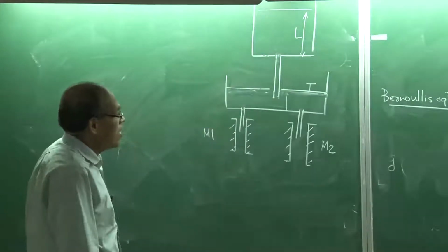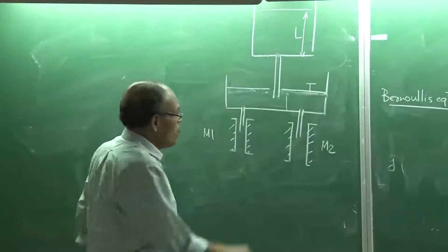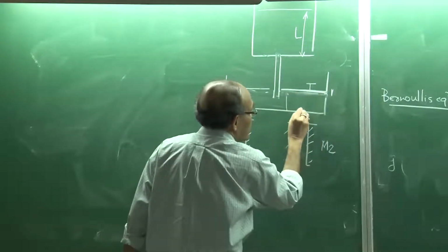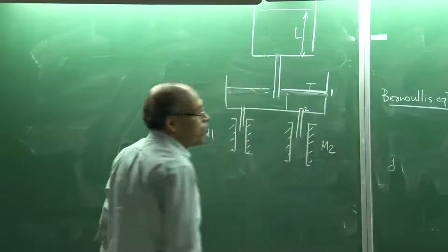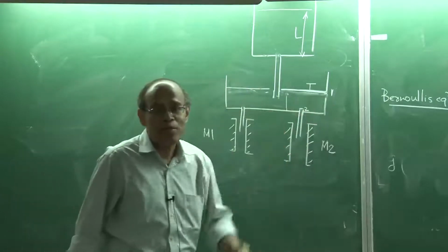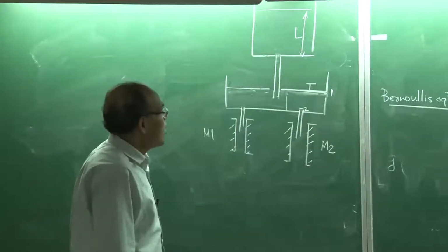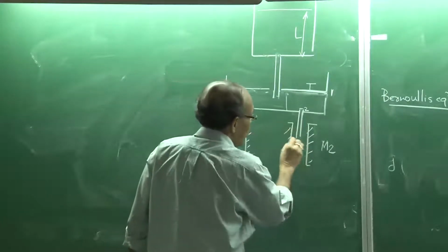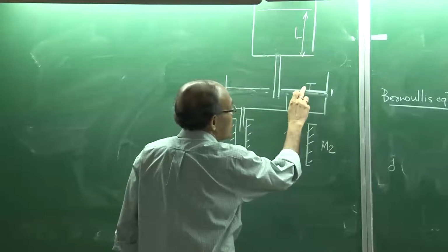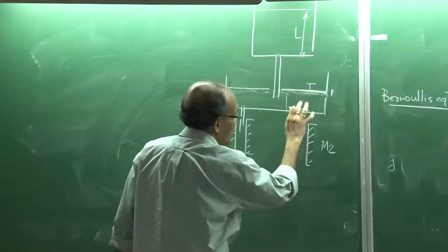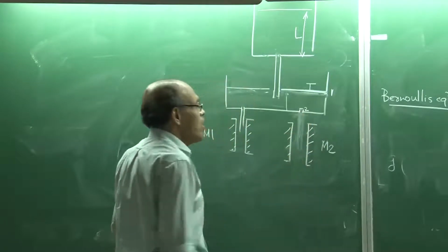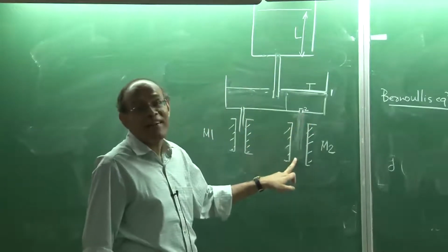Now, if you consider this surface as surface 1 and this outlet as surface 2, and you apply Bernoulli's equation here, okay? And then you can say that look, the discharge here is also under atmosphere, the pressure here is atmospheric pressure. If you consider that this nozzle stream of molten metal is in open air, the way I have drawn it, it is an open air tubing.